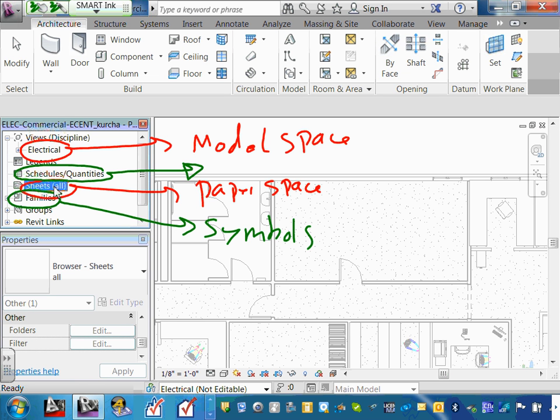You put it inside the panel. In CAD, you have to write everything by hand. In Revit, you circuit and you hit a button, and it will generate the panel schedule for you. But where does it drop the panel schedule? Under Schedules, right here. So these are panel schedules and others. If you want a mechanical schedule, guys, it also does mechanical schedules for you.